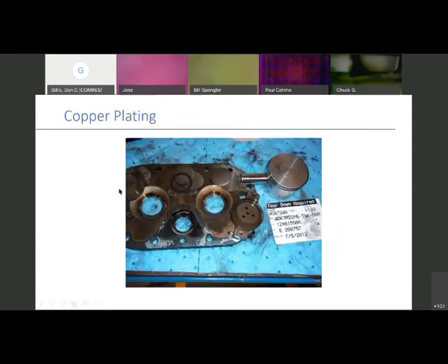I like this. This is one of my favorite slides when I'm presenting this section. This is a nice slide, and what this is, is moisture. This is from pore evacuation, and we're going to talk about this next week if Julie wants to. This is moisture inside the system, okay, and high heat, and we call this copper plating, okay? But what I really like about this slide is here, obviously they didn't pull down to 500 microns or less.